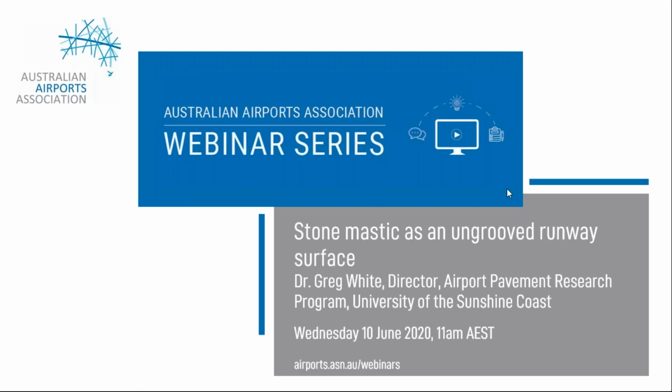Thanks, Greg. On to the next question from Filippo. The surface texture is not dissimilar to the coarse gradation Superpave mixes we trialled in New Zealand in 1998 to 2006 and could comfortably meet friction test requirements without grooving. Those mixes were difficult to compact during placement. The SMA high bitumen content is very attractive from a longevity and resistance to weathering effect. What is the modulus stiffness of the SMA mixes versus DGA?